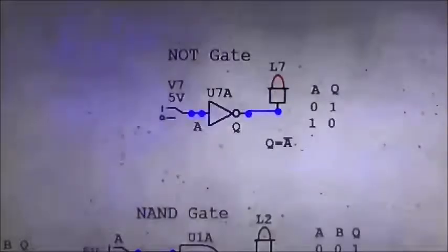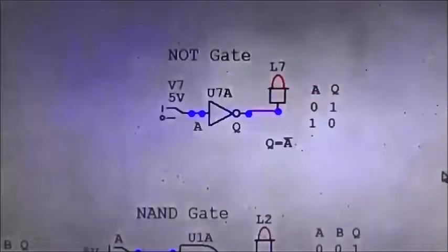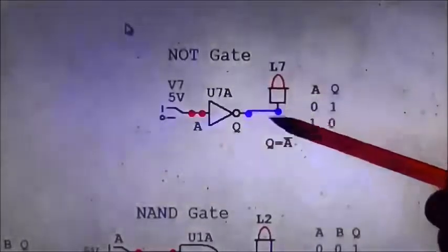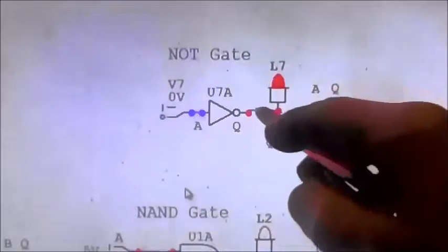And so we'll begin then by looking at some gates in the simulator, and there are really only 3 kinds of real gate, although you can put them together to make lots of different others. So what we've got here is the NOT gate, which is the most basic. It's also known as the inverter, and we'll see why. If we start the simulator running, we'll see that we've got a 5-volt logic input, that's high, but the logic output is low. If we turn the logic input to low, the output goes high.